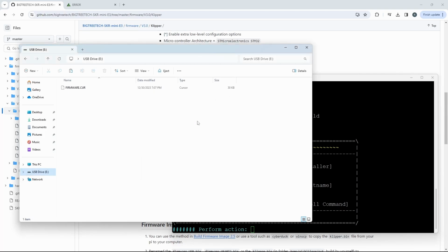So if you're using a larger card, most times 16 gig cards will work too, but you want to have a small card because some boards can't read large SD cards and you have to get into partitioning them and all sorts of stuff. So I recommend having some really small SD cards lying around, 8 gig or smaller, so that you can do this.